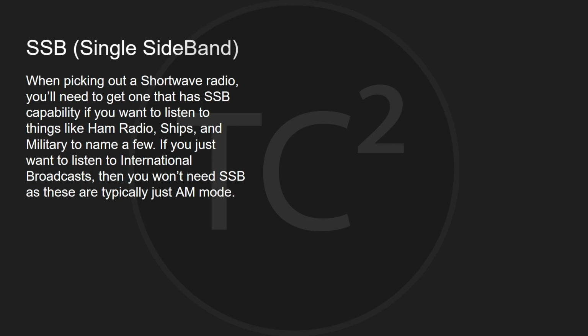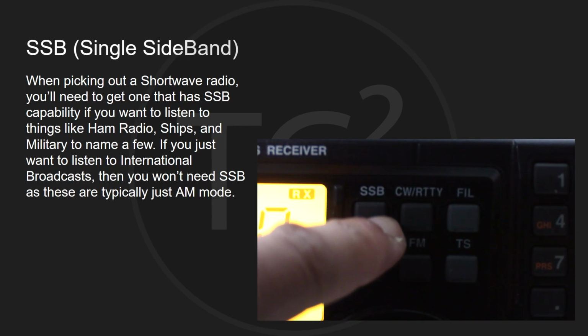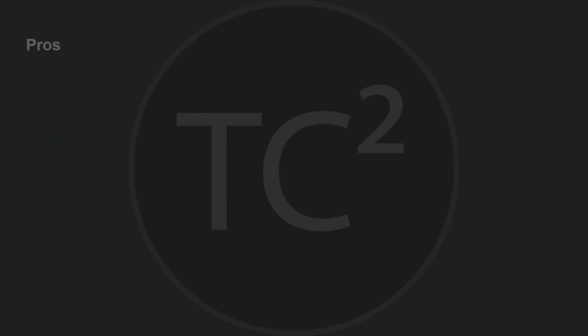Now, one important thing to note when looking for a shortwave receiver, you'll usually see options that don't include SSB, which is single sideband, or sometimes just referred to as sideband. And they only offer AM mode and sometimes FM. Now, if you're wanting to listen to more than just the international broadcasts and be able to listen to things like ham radio, ships, and the military, you'll need a shortwave receiver with SSB capability. Now, on to some pros and cons for shortwave radios.